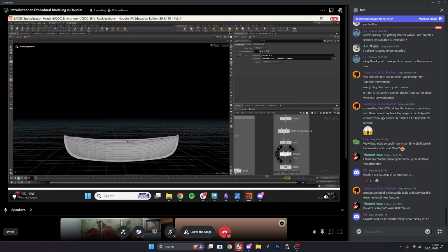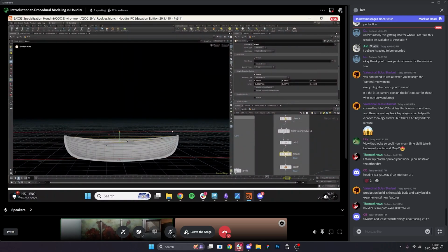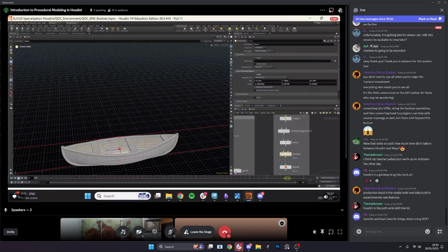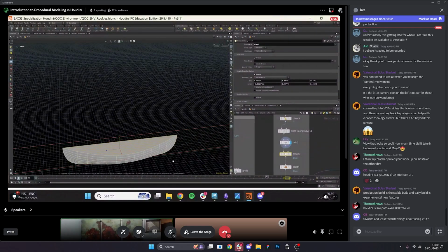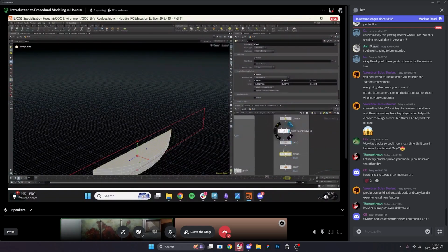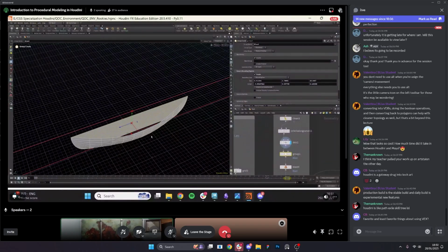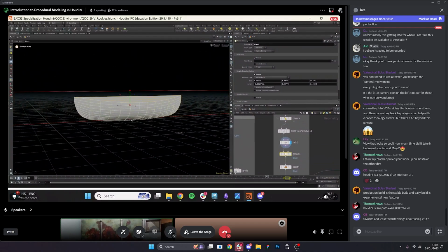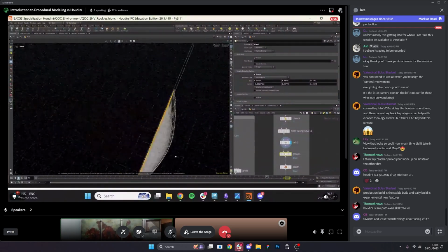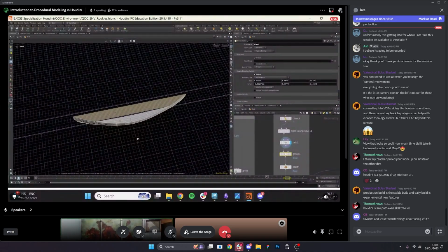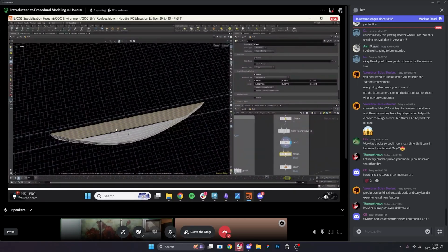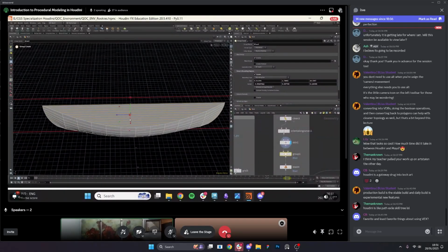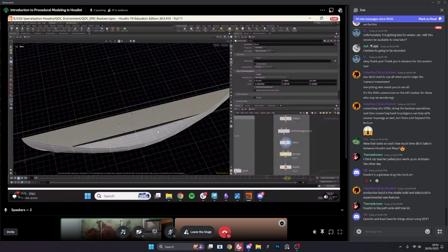Here's one of the mistakes. When I did the skin, so the skin basically adds a skin to the curves. Now, due to the fact that I used separate curves for the front and for the sides, the point numbers don't quite line up. There are ways around this. I, again, did not have time to fully explore that.